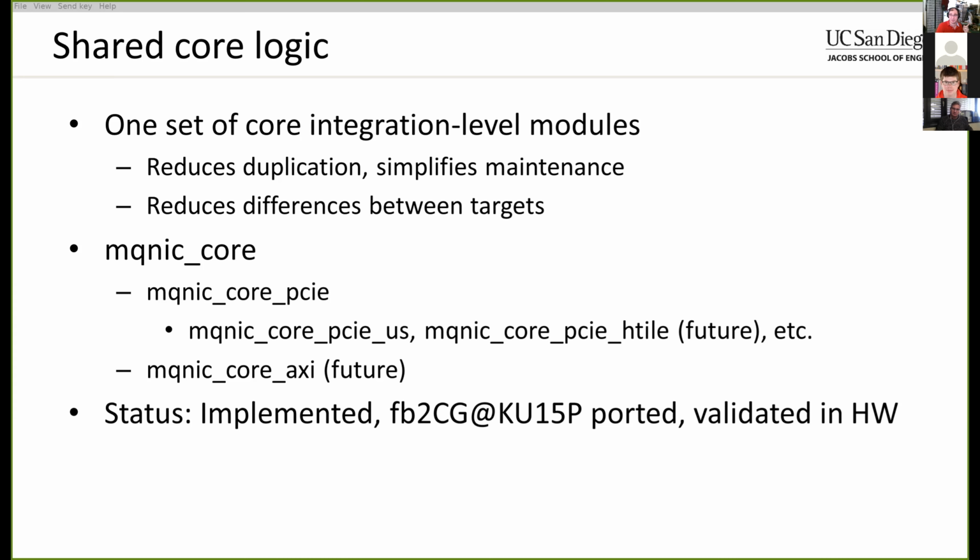So yeah, I have made a couple of changes that were kind of departing from how things are currently designed. One of the changes that I made is that I've also pulled the asynchronous FIFOs inside of the core logic. And this is done for a couple of different reasons. One of the reasons for doing this is then you can provide, if you want, the direct MAC connection to the application block. So if you're trying to do something really low latency and you want to connect directly at the MAC interface, you can do that. And if that was outside, then that would be more difficult.